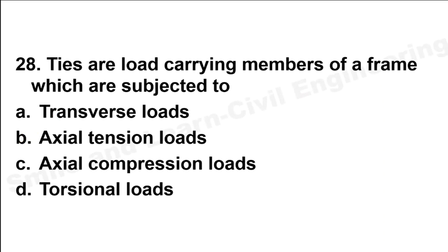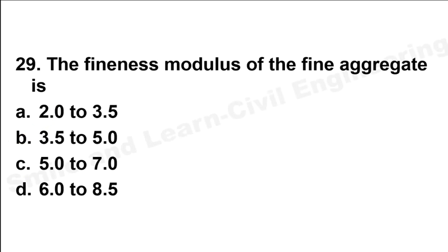Next question, ties are load carrying members of a frame which is subjected to axial tension load. Option B is the correct answer. Next question, fineness modulus of fine aggregate. We all know that fineness modulus of fine aggregate is 2 to 3.5. Option A is the correct answer.